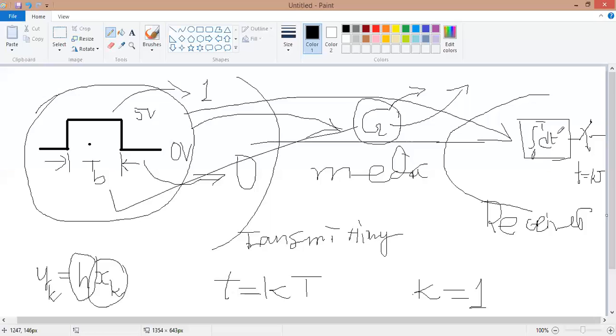Every time, in case of a superheterodyne receiver, before the detection we need an RF amplifier. That means the received signal may be amplified. So the amplifier is part of the receiver, and it is used to enhance the voltage or energy level. Otherwise, some attenuation may take place and you will get a very, very feeble signal, which is not our main objective to receive from the transmission section.